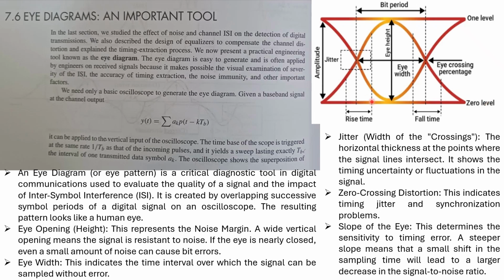So like here, the overall summary is, this is your eye diagram where it represents the 0 level and this is the 1 level. It will take some time to go from 0 to 1, and it will take some time to come from 1 to 0, and if you combine the multiple signals, then automatically this will form the eye type of diagram. Ideally it should immediately go to 1 and then come to 0, and it should come 0 to 1.